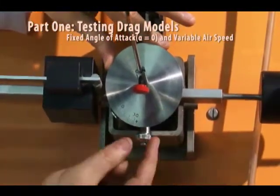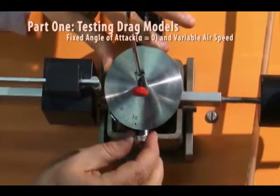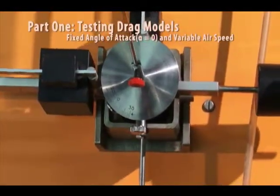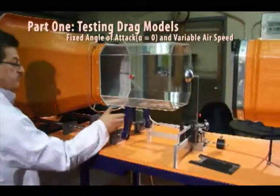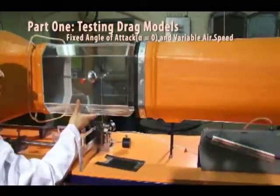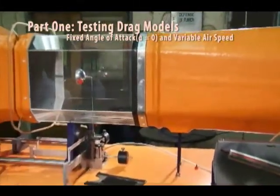All these arrangements should be done with no airflow to provide axisymmetric flow over the model. Close the testing section and don't forget to close the slot in the tunnel base using the cover plates to reduce airflow turbulence.